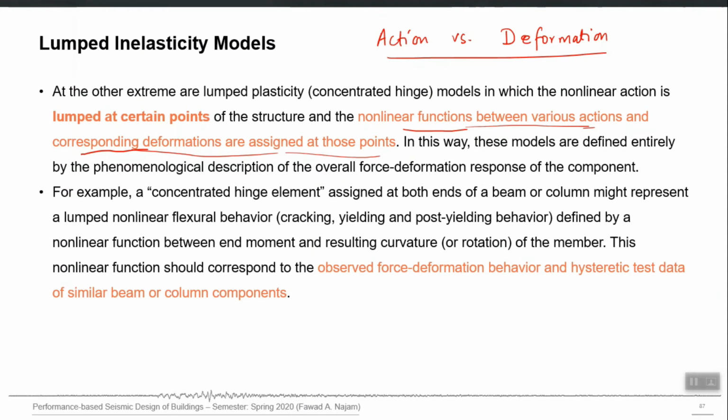You can have even closed form expressions. For example, let's take the example of torque and twist. You have seen this formula TL over JG. This is theta. For any applied torque T to a shaft having a length L, the torque angle which it will produce is this one.